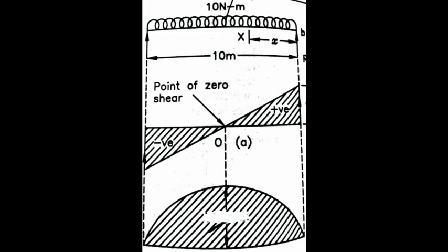You should remember this point for your future examinations or an interview. When asked where the BM is maximum, you can answer that where the shear force changes its sign, the BM will be maximum. It should be remembered. In the next slide we can discuss more complicated or different problems one by one. So thank you.